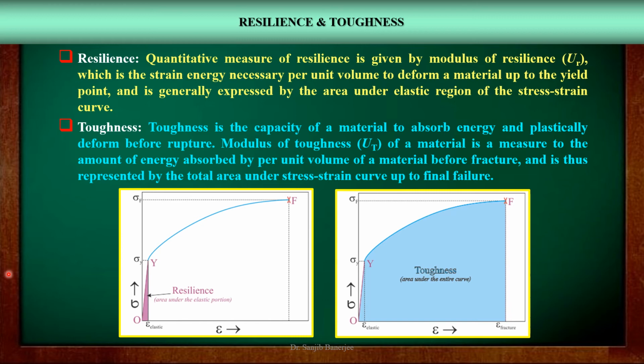Thus, the modulus of toughness can be represented by the total area under the stress strain curve up to final fracture or failure.